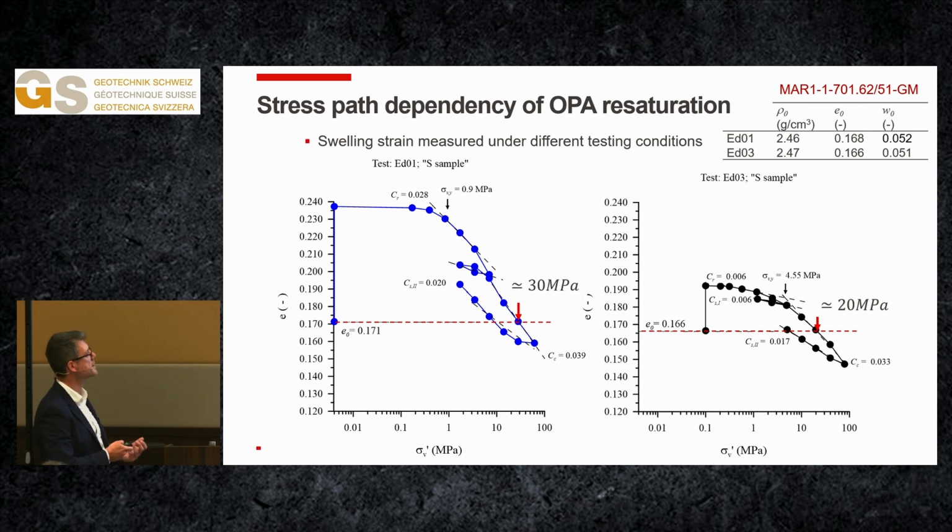And just to give you an example of how important the swelling can be in this material, those are two practically identical samples of Opalinus clay that are let to swell before they are compressed at two different stress levels. So you see the stress levels are quite low. Here we are talking about a few dozens of kPa, here just some kPa. You see how much the material can swell, you see how much even a few kPa of confining stress change completely the response of the material.